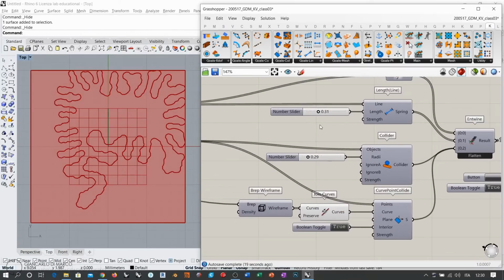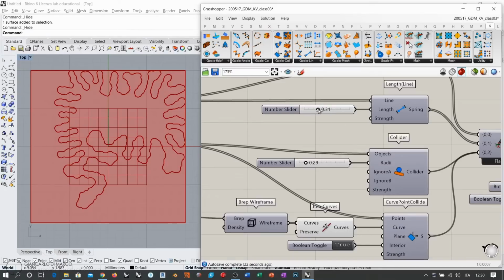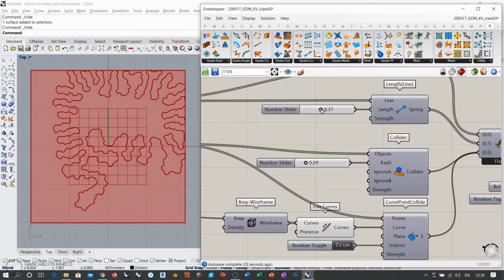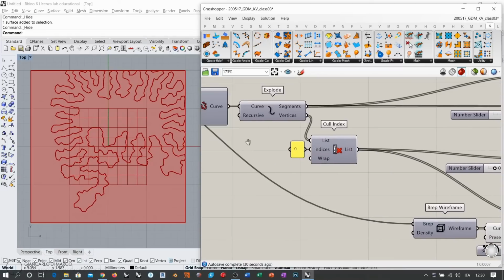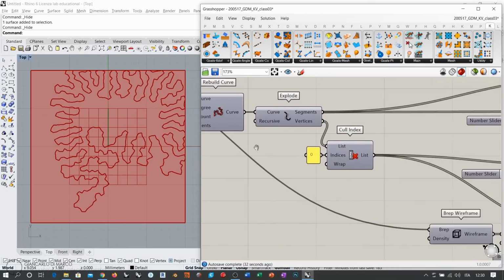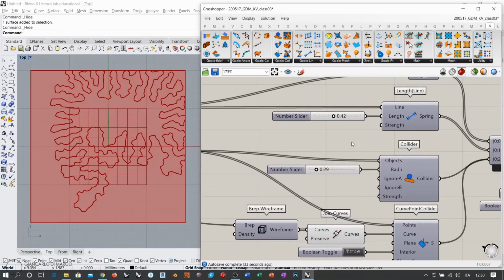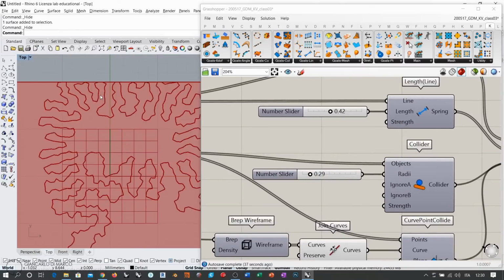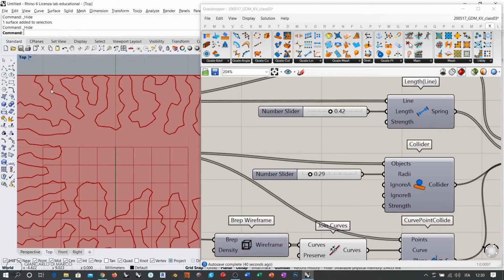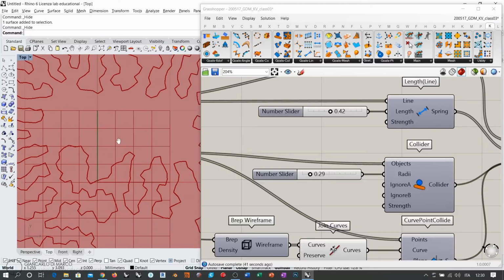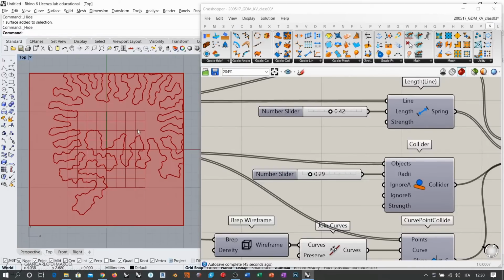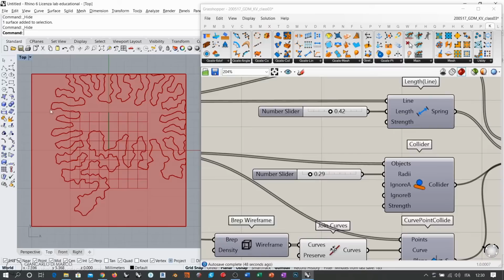Now you see that as we are expanding and adjusting the polyline, we already have quite a huge amount of segments. There are 600, but you also see that they tend to behave like polylines. So you always see these vertices and these segments, which are basically assuming a random mutual inclination or angle. So what we can do here is eventually try to smoothen this curve.